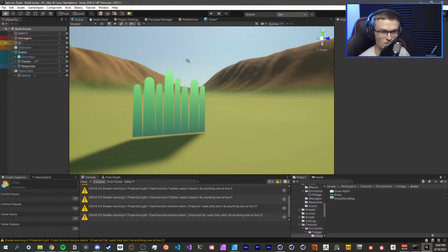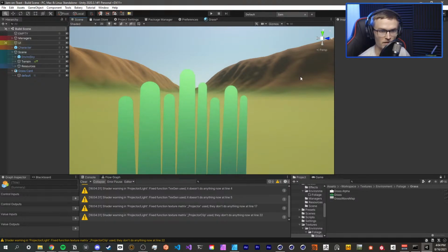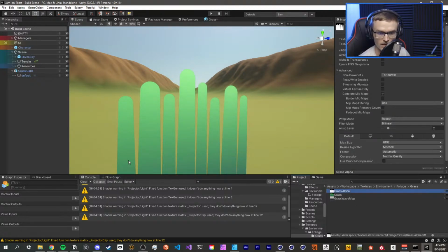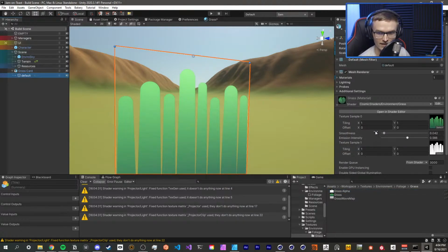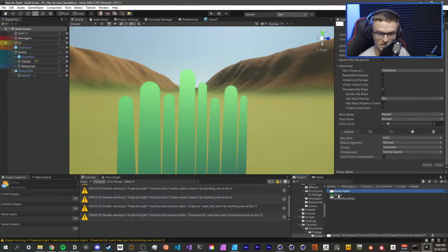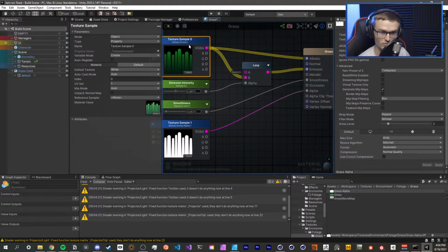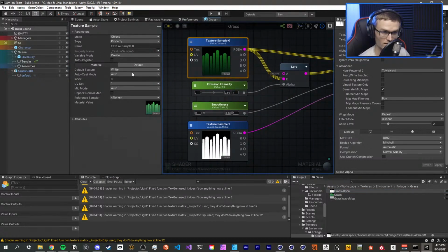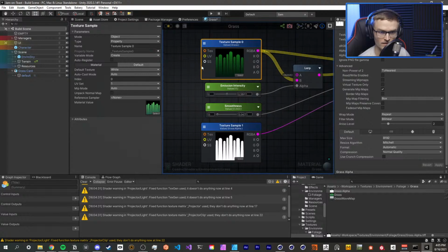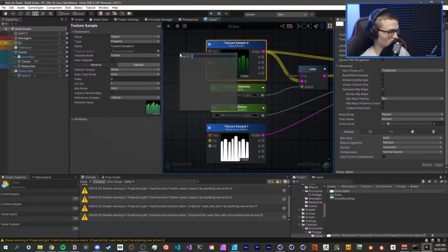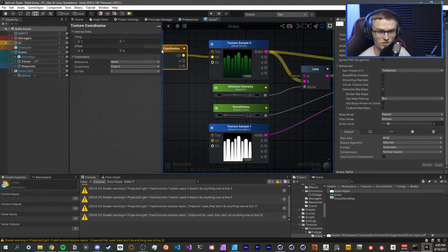So, we are getting a wrapping issue. You can see this like 1 pixel up here. And there is a hacky fix to that, to offset the tiling. But what I want to do instead is look at the shader and see if I can prevent these from tiling. So I think they are auto tiling. All right, UV. I want the texture coordinates there.